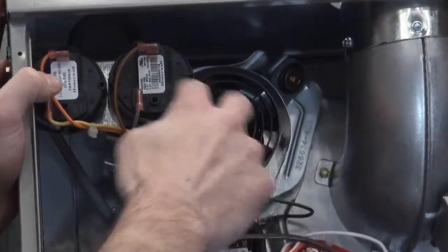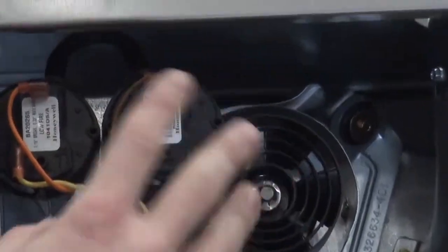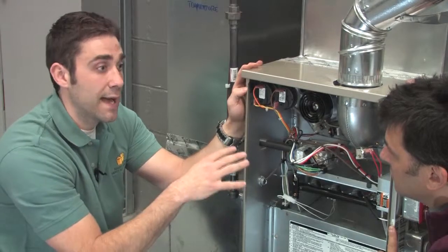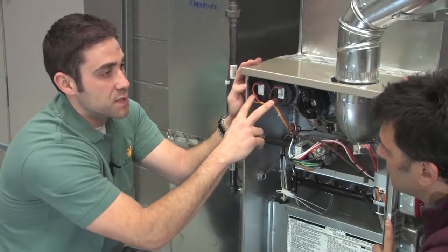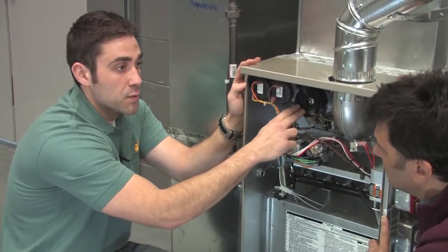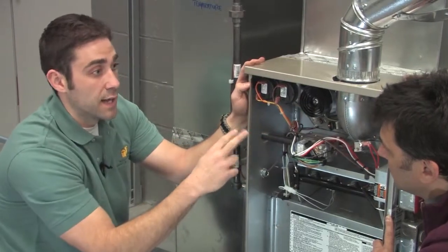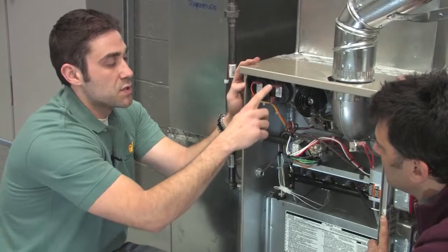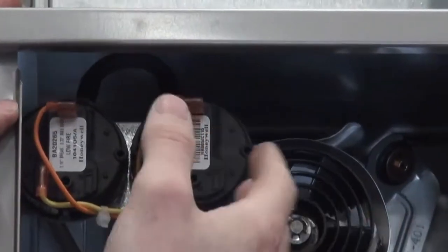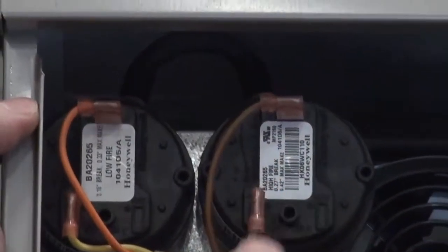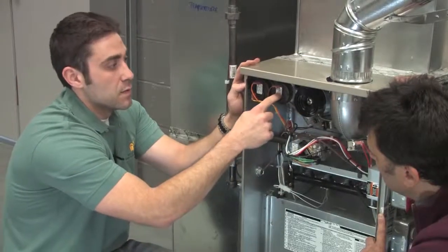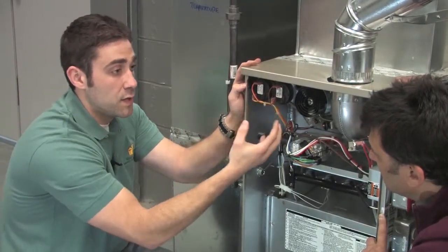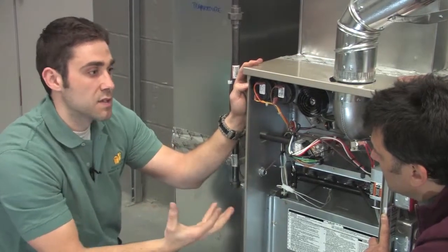So this fan kicks in and there are two pressure switches. This system is a little more complicated in the sense that it's actually two stages. There are two firing rates on this, a high and a low, so you have two pressure switches to sense that. The flow rate through the heat exchanger is going to be different on high and low: slower on low and faster on high. These switches are set up to prove that there is no blockage in the heat exchanger. So this fan kicks in, the pressure switches prove that there's no blockage, we have good flow through the heat exchanger, and that'll start the ignition sequence.